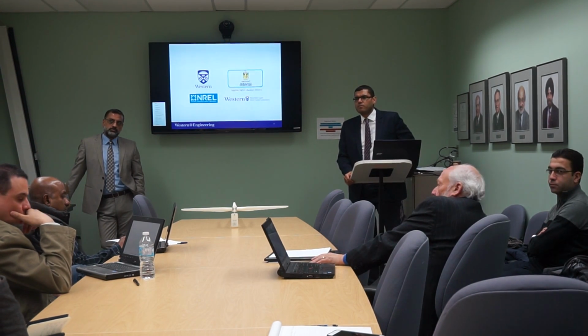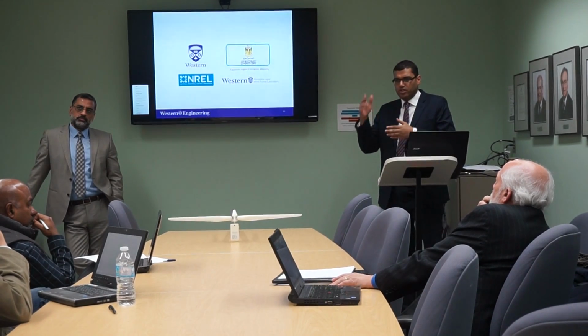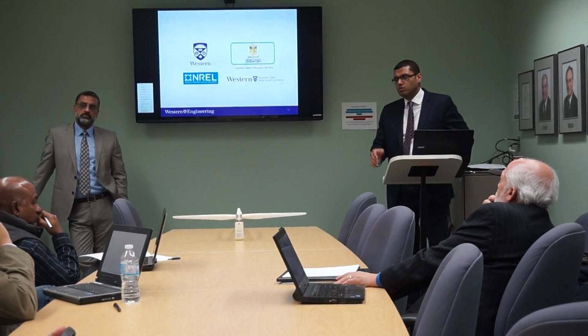You said that they increased the pile diameter from 4 meters to 6 meters. Did this increase come mostly from the vertical load or the lateral load? Lateral load, because of course we have two components, vertical and lateral, but the main thing is lateral load.